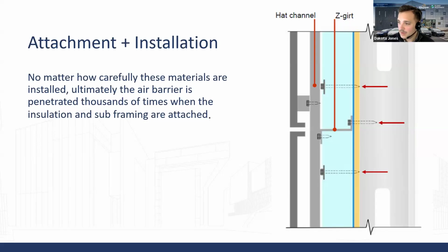We can look at this typical wall section of a multi-component system. We have our backup wall doing great, supporting that rain screen. We got our air gap, everything's rocking and rolling. But we have this very important insulation layer, which is going to protect this backside from getting cold. If this backside gets cold, condensation can occur on this side and this side.